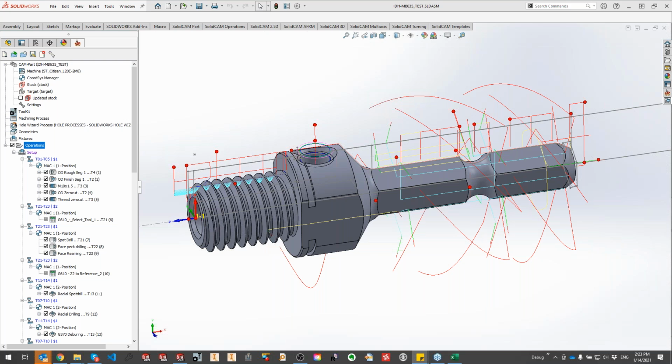Before developing a post processor, for each machine you definitely need to have a programming manual. This is very important. Then there should be G-code examples, some photos from the machine itself, and the 3D models if your customer wants machine simulation with it.